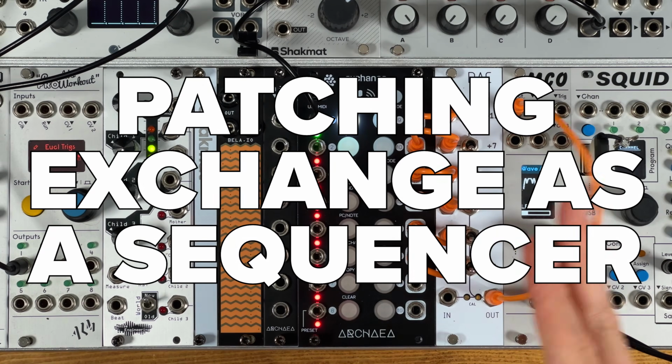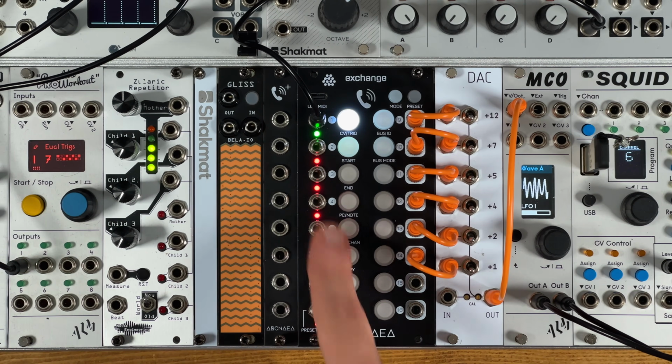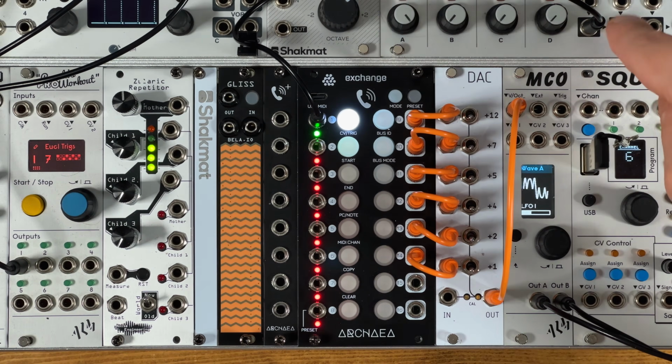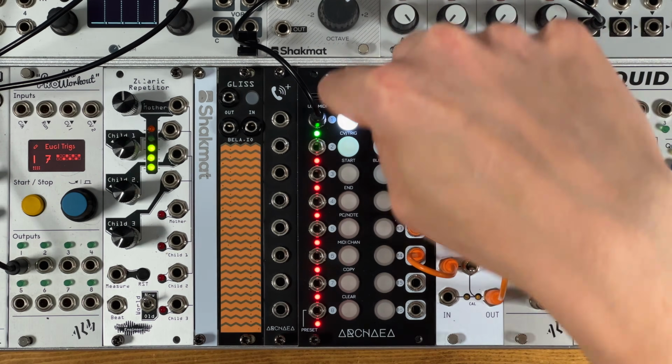So it's even possible to patch Exchange as a kind of crude sequencer, and there's a couple of different approaches to this. One would be to use the previous sequential switch patch I kind of demonstrated and feed a number of different offset voltages into the inputs and then step through them in turn at one output. I'm going to try a slightly different approach where I'm going to feed in a continuous 5-volt signal to the input, just generating that with an offset from Quadrat.